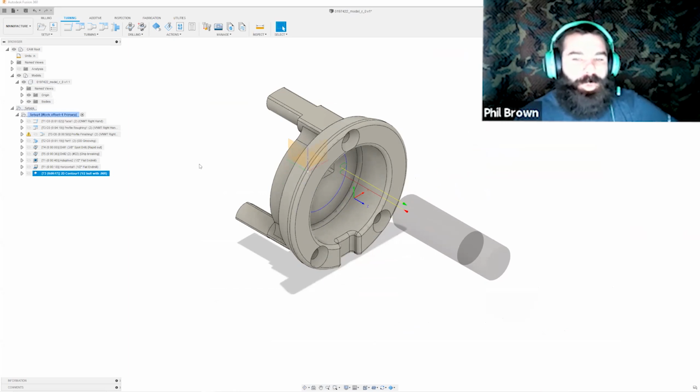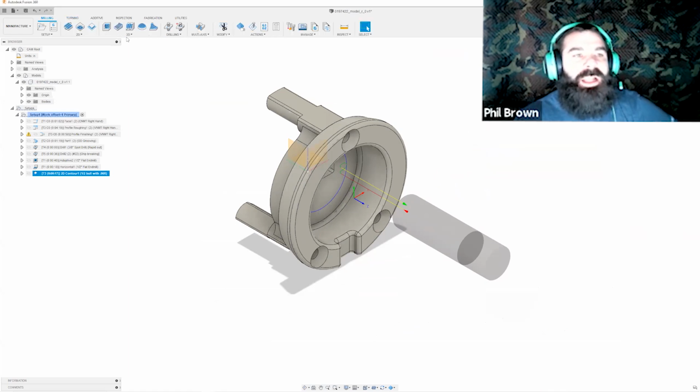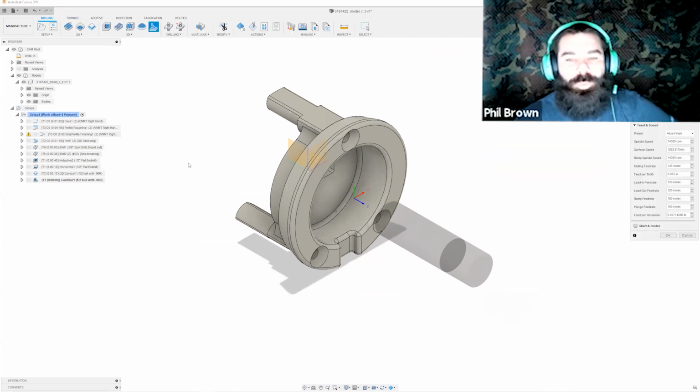Ideally, since I have the bowl end mill out, let's do a little fillet cleanup on this inner fillet. So I'm going to go ahead and jump back into milling. Let's use a 3D contour toolpath. This does come standard in Fusion 360 for free. Everything I have done up to this point is the cost of just a standard license. Nothing is an added feature.